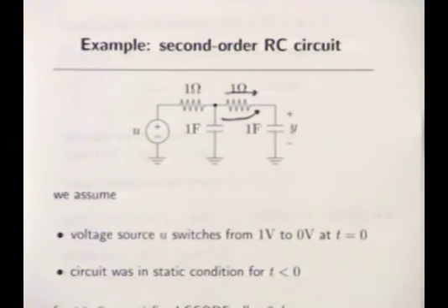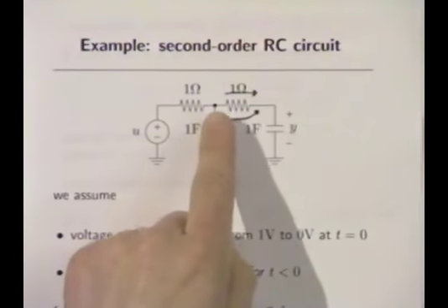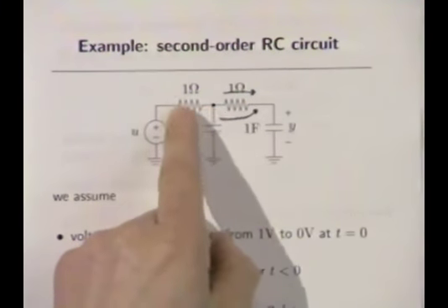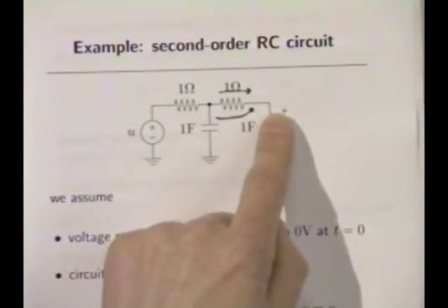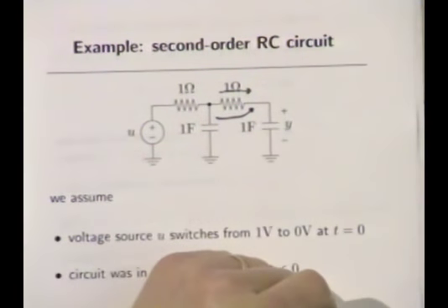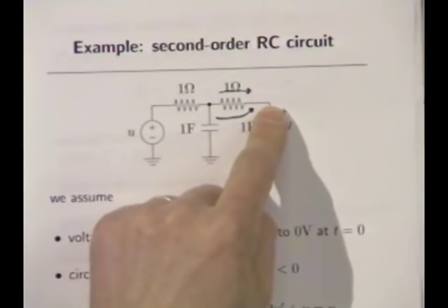4 seconds, right? Now the only minor problem with moving that capacitor there is it completely changes the circuit. But then you think, okay, well, moving that capacitor over for the convenience of being able to solve the circuit, what did it do? Did it make the circuit slower or faster? And you think carefully about it, and you realize, oh, that made it slower, right? Because here, this capacitor only has to charge through an ohm of resistance. I move it over here, and I have to charge through 2. So by moving the capacitor over here, I made it slower.